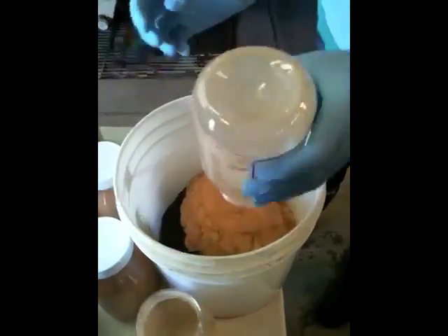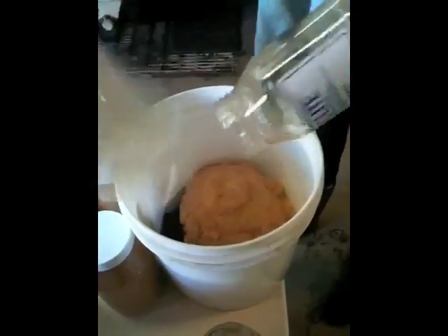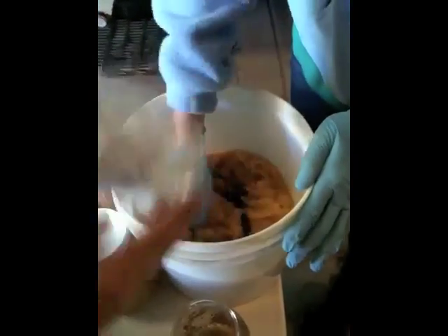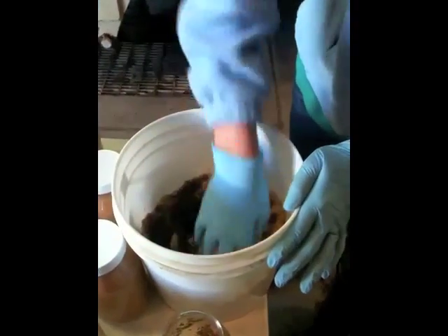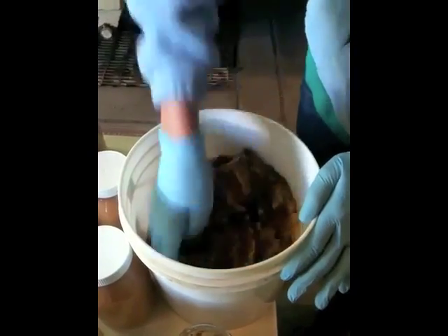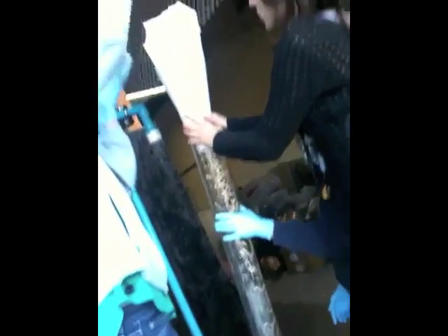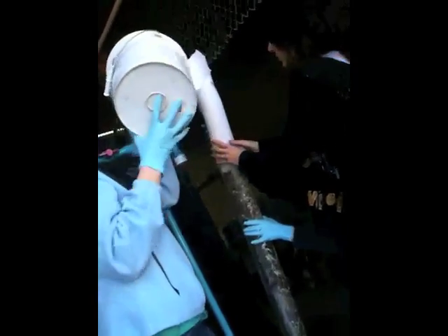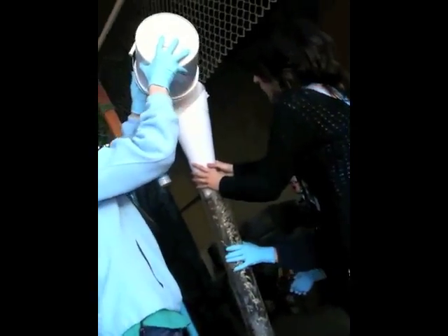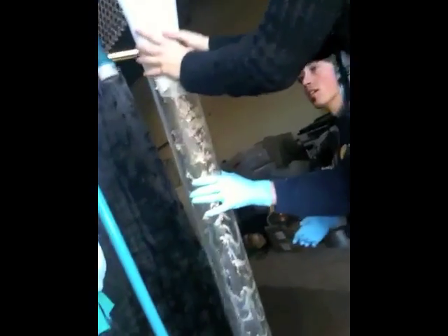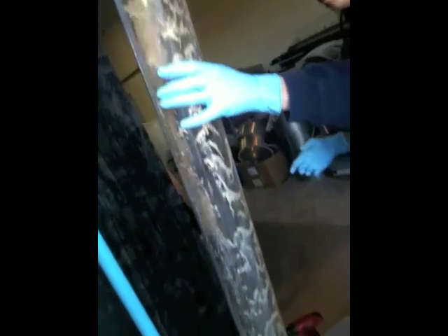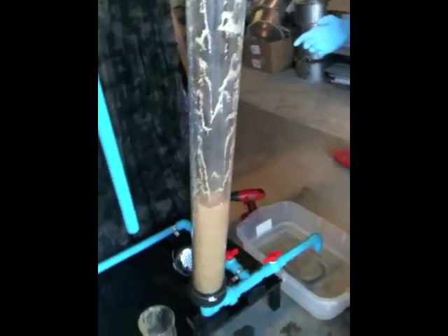Two resins were chosen for the prototype application: UltraClean UCW 5072 and UltraClean UCW 9126, which are designed to work in a mixed bed together. 5072, the anion resin, has a minimum capacity of 1 equivalent per liter, a moisture retention of 55 to 60%, a diameter size of about 605 micrometers, and a specific gravity of 1.07.